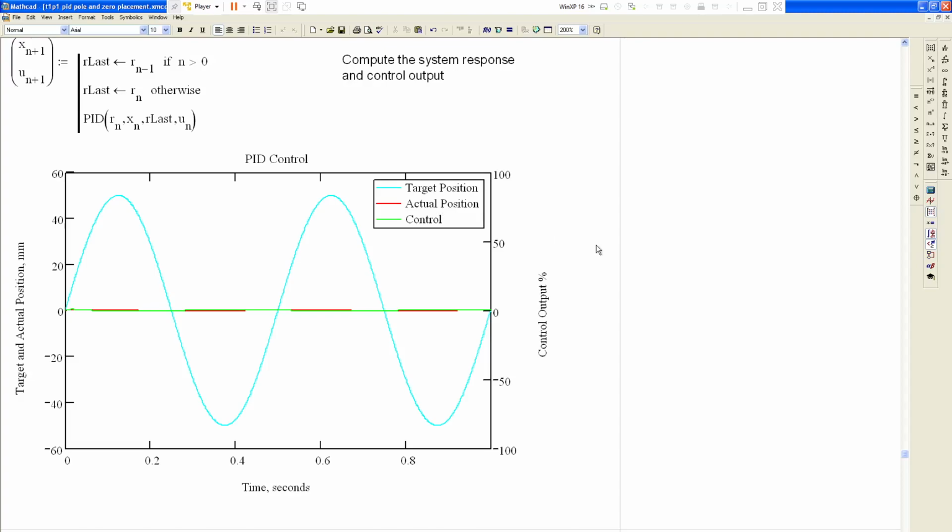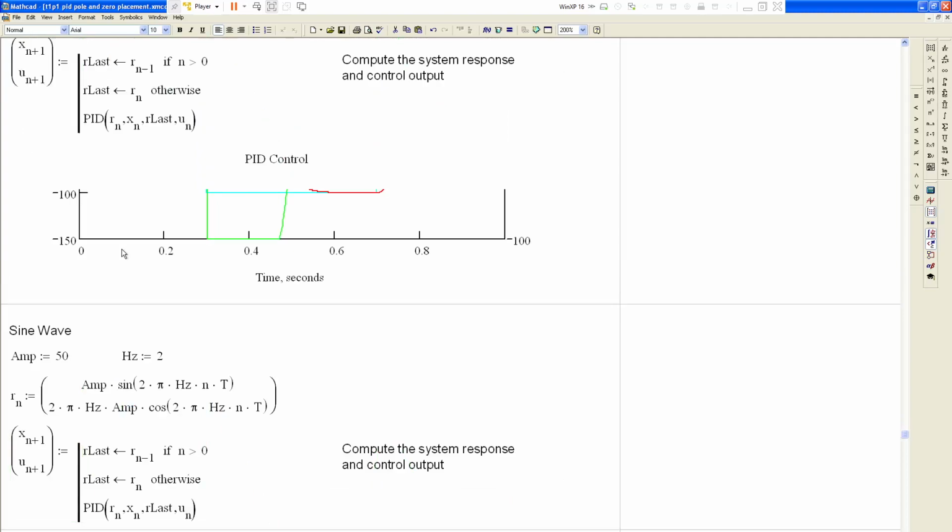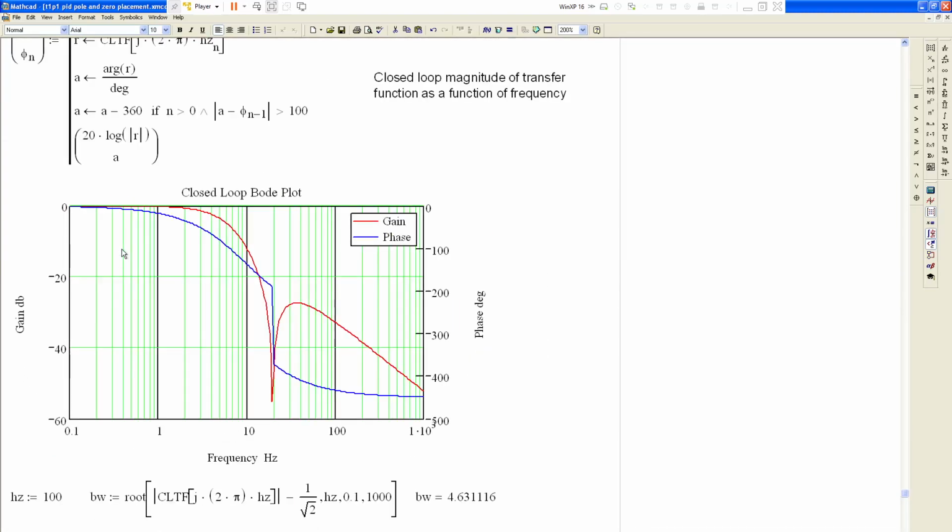And we have used this a couple times in the past, normally just to make it so that the motion controller doesn't respond to machine resonances that happen to be around 8 to 10 hertz. And you could use it to reduce 50 cycle or 60 cycle hum too, if you happen to have a feedback that's susceptible to that. So now let's go back and put that back equal to, let's make this 20. You can see that it's moved up to about 20.